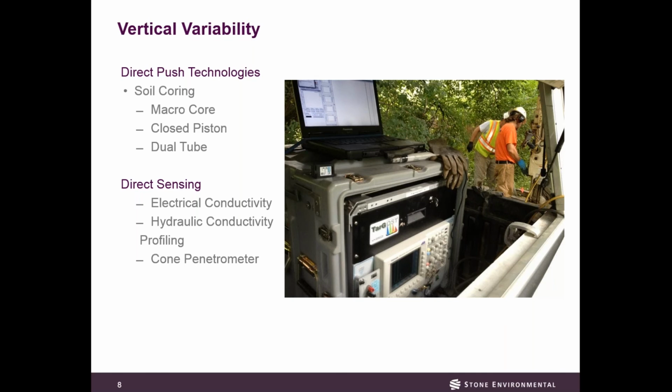As Seth mentioned, the EC, electrical conductivity, doesn't work everywhere. It relies on a dipole, so sending electric current between a dipole on the probe. And in New England anyway, you have a lot of fine materials that are generated from feldspars and quartz. And so these glacially derived fine-grained sediments, the mineralogy variance between that derived silt and clay versus a phyllosilicate silt and clay is very different. There's a lot more iron, obviously, in the phyllosilicate, so they generate a lot more EC signals. So you see a lot more variations when you have a mineral clay versus a glacially derived clay.